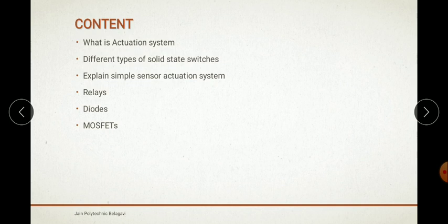Next comes the solenoid. So what is this? Solenoids consist of a coil which is energized. When the coil is energized, the EMF is induced. Then, when the EMF is induced, it makes the core move to increase the flux linkages by closing the air gap between the cores.